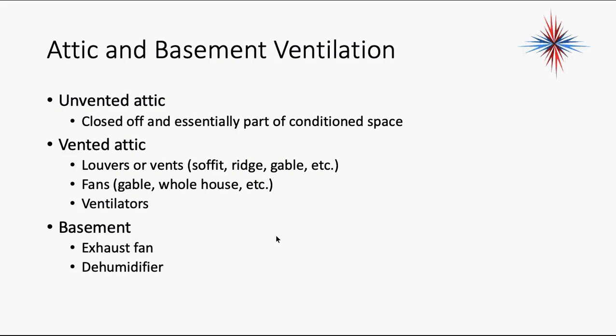Okay, if you have a crawl space that's vented properly, you can have cold floors if the insulation is not all that great. Ductwork that runs through crawl spaces has to be very properly sealed. This is one of our biggest problems, especially if you're working in an area that has a lot of mobile home parks, or double wides or single trailers that sit up on blocks.